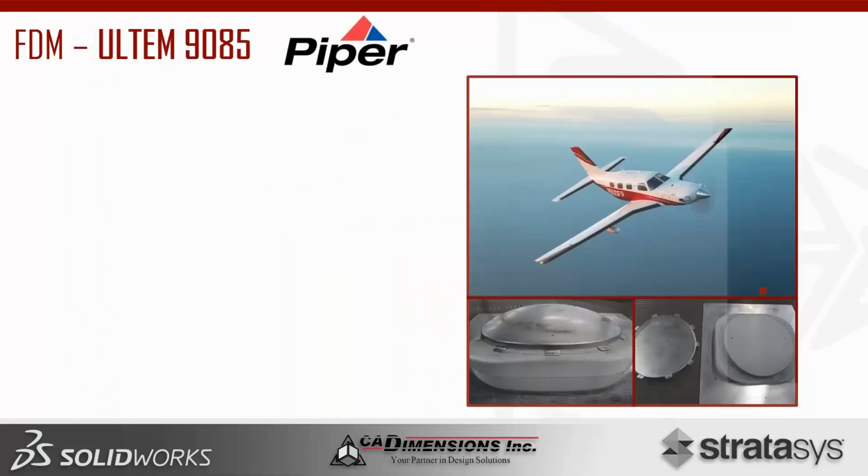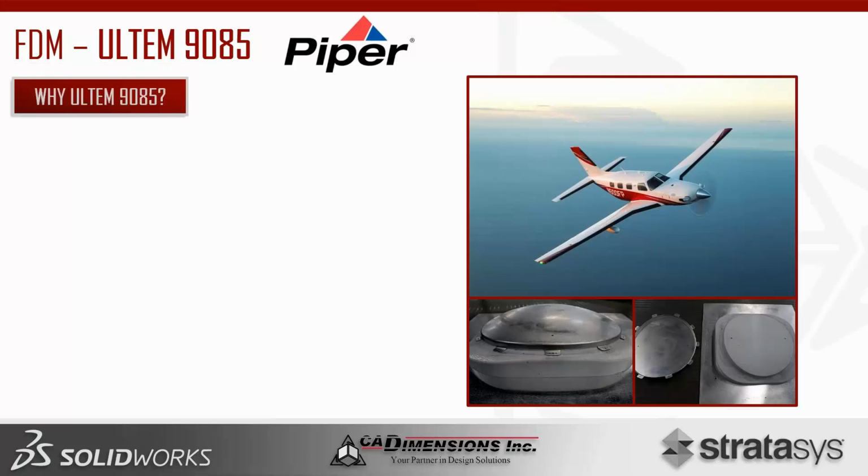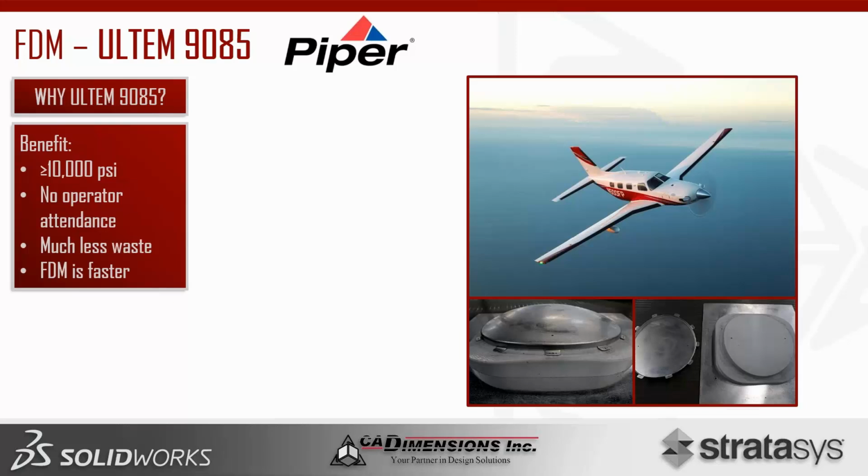And one example we have for you here is Piper Aircraft, based in Florida. They make single and double engine personal aircraft. So why do they use ULTEM 9085? A couple different reasons. One being that they were able to get 10,000 PSI resistance or more based off of this material. They also didn't need an operator in attendance. We essentially have lights-out manufacturing, so you could start a 60-hour build on a Friday afternoon and come back Monday morning and it'll be completed with no issues, not having to babysit your parts.